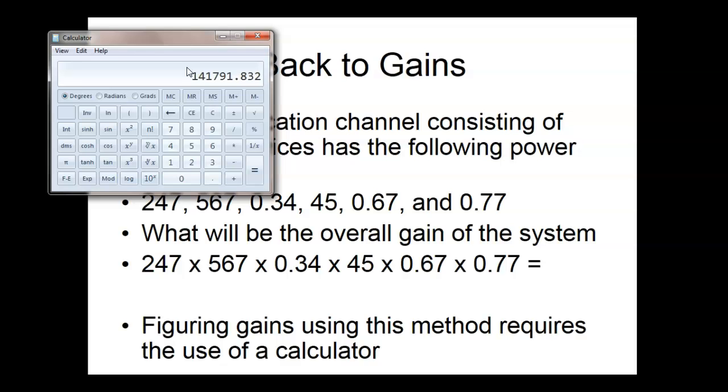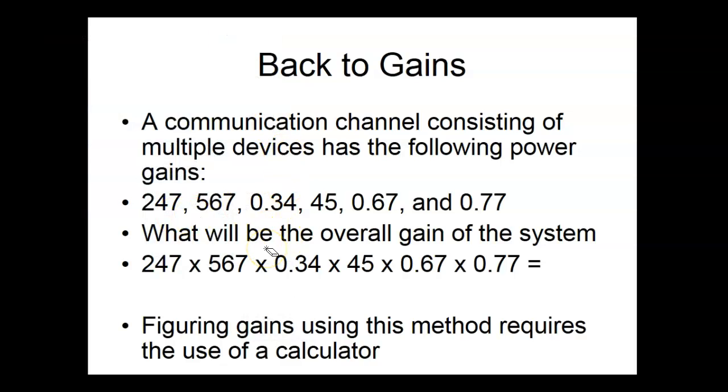I might be putting 100 milliwatts in and getting 1,000 milliwatts out. But that power is being provided by a power supply. So amplifiers, all it does is manage the power that's already there. If they created power, that means you could go out there and disconnect your battery, disconnect your alternator, and turn on your radio and it would work. So those devices don't create power, they manage the power that's already there from the power source. So, like we said, this requires a calculator. When we start dealing with these complex gains and attenuations, it's going to require a calculator.